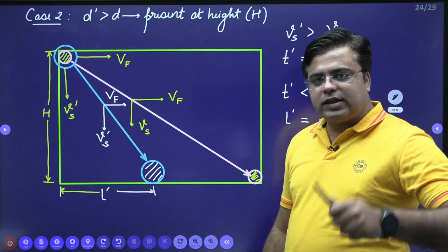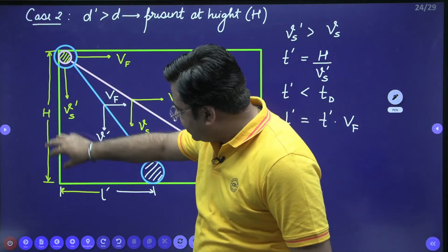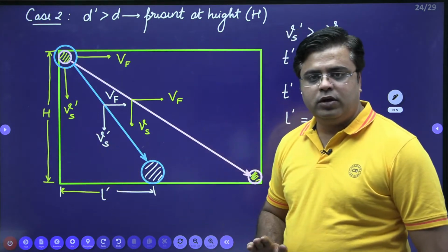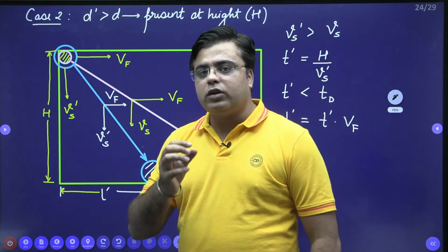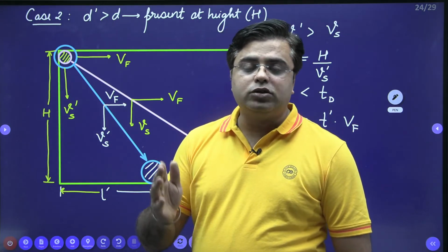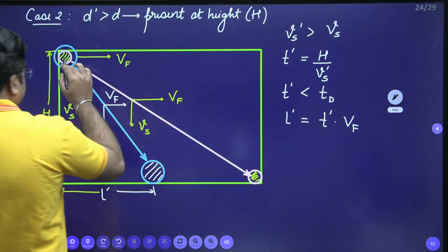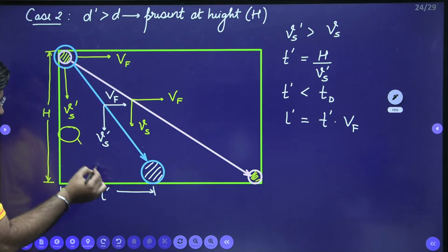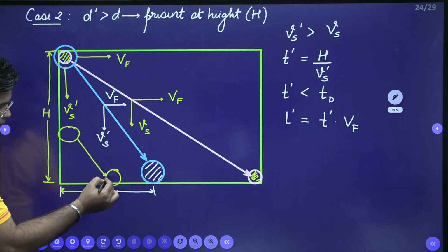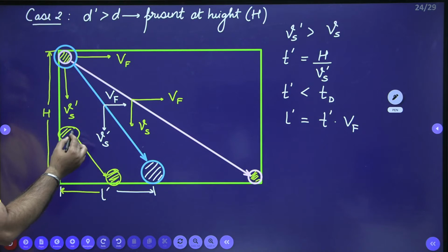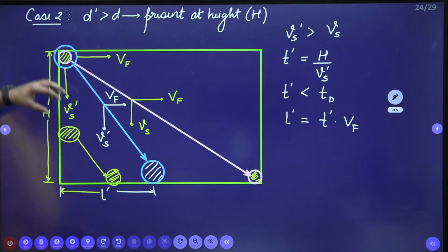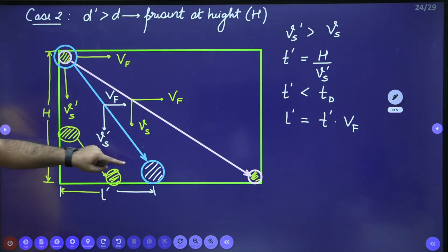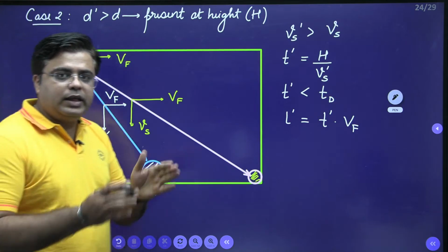Now if this larger size of particle is present anywhere in this height, it will reach the bottom of the settling zone in lesser time. So particles of size more than the concerned size are also 100% removed. If you consider the same particle at some smaller height, right? This will also travel like this and reach the bottom of the settling zone. So for larger size of particle, it doesn't matter if they are present at capital H height or at some small height h, all these particles are reaching the bottom of the settling zone in the given time.